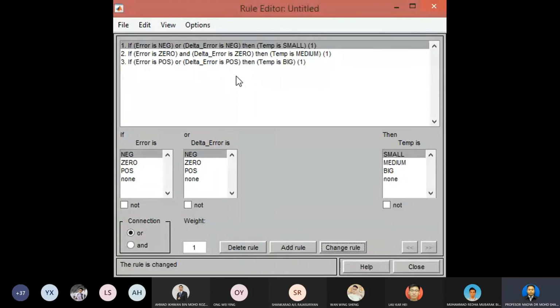Normally the rules will be fixed. That's why I mentioned to you, we just follow the default rules. For example, we have 9 rules, just follow the 9 rules, and we just adjust the range for the input and output. For example, before this you set the output as 0 to 10, maybe you can try 0 to 100, or 0 to 1000. Change the range, or you can adjust the mapping, shifting to the left or to the right. This is how to tune the fuzzy logic.